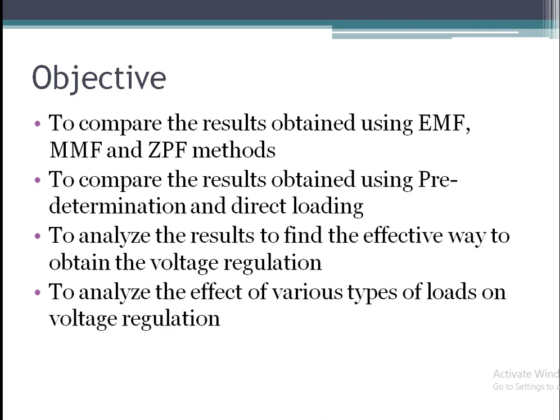The objective of carrying this out is that after completing the experiment, you have to do the calculation to find the voltage regulation using EMF and MMF. After that, we are going to compare the voltage regulation obtained using the EMF, MMF and ZPF methods. Then you have to compare the voltage regulation obtained using predetermination with the direct loading method.